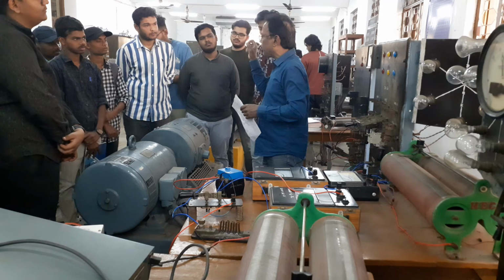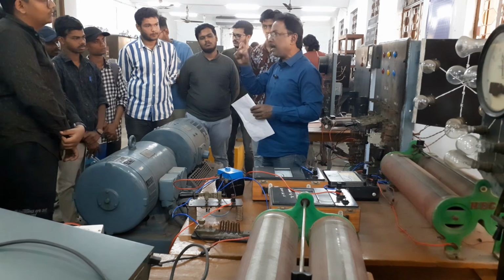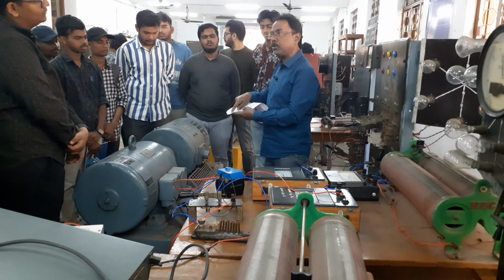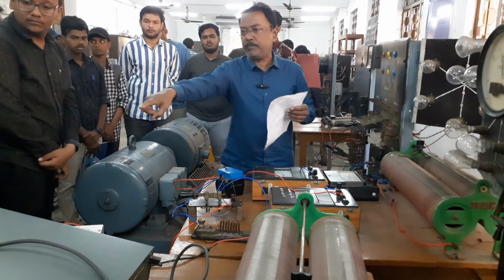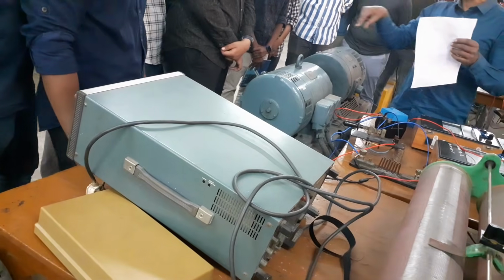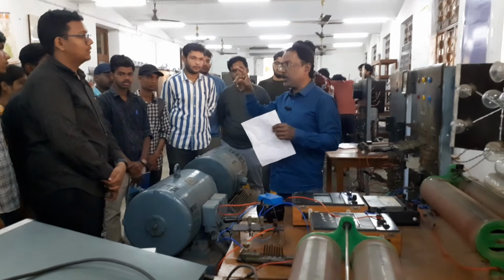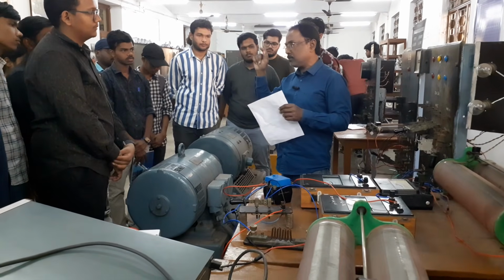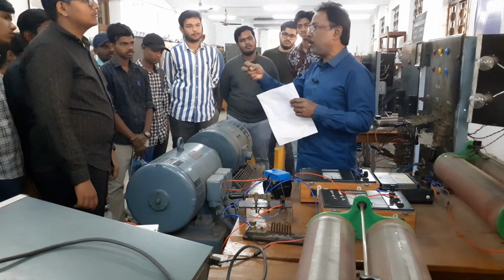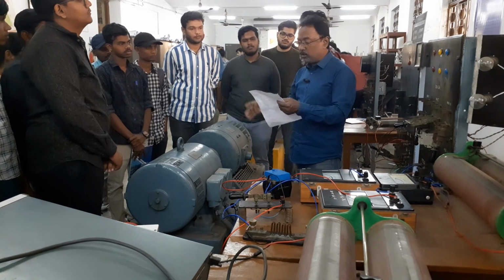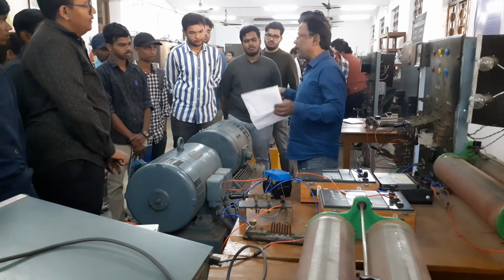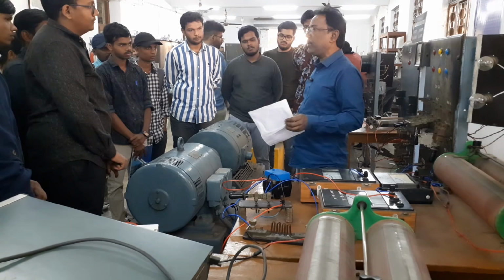Here you are doing it for three phases for a moment only, a very small interval of time. At that time, you have to catch the waveform. You have to store that waveform by using the storage oscilloscope. This is the storage oscilloscope. It is very simple, just like your general oscilloscope, but the storage facility is there, and other features are there. So finally, you have to store the waveform for that moment. You have to short circuit as per the instructions given in your instruction manual.